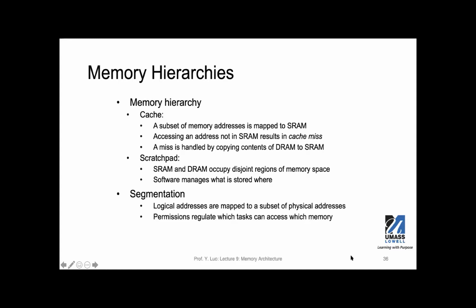Scratchpad is a little bit different from cache, even though both scratchpad and cache are based on SRAM. Scratchpad uses a separate address space from the DRAM. In contrast, cache shares the same address space, even though cache is much smaller than DRAM. So that's a major difference between the cache and scratchpad.